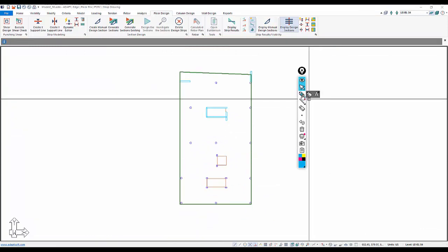We know in this particular example, we're going to align the banded tendons in this direction. We'll just assume this end here is the dead end. We have a live end. The spans are short enough that we can stress from one end, and we'll do the same here. We have a banded tendon here. This area gets a little bit interesting in terms of the post-tensioning, but we're going to make a decision where we can stress in the openings. So maybe we have another banded tendon here that's stressed.